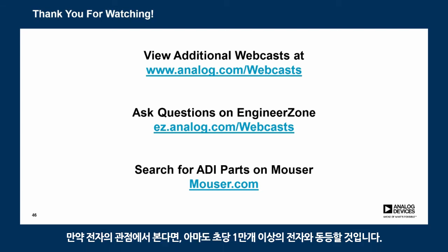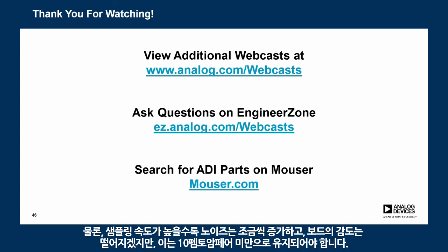If you want me to put it in terms of electrons, this would probably be equivalent to 10,000 plus electrons per second. For higher sampling rates, the noise would be slightly higher and the sensitivity of the board would decrease, but it should still be less than 10 femtoamps or so.